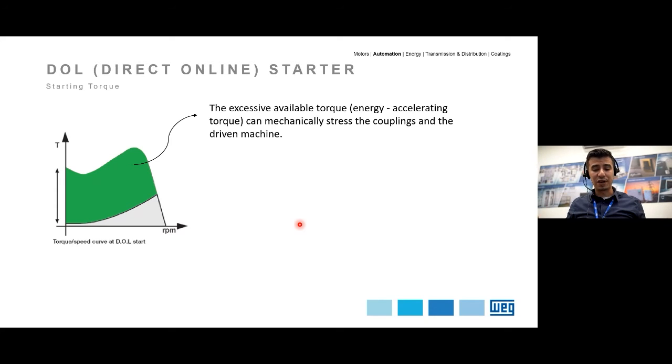So stress might be, for example, if you have a gearbox, your gears will go from 0 to rated speed very quickly, and then you might have something like a kick when starting. And this kick, this abruptness, this aggressiveness might bring mechanical fatigue or wear to the mechanical parts of your application. So in this example with the gearbox, you might have mechanical stress on the gears themselves.